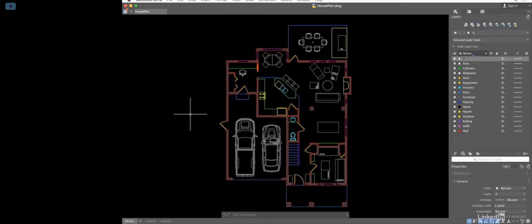that your CAD program can export to a format that SketchUp Pro can import. And I'll be using AutoCAD's native DWG format for this purpose. Most CAD programs will either support DWG or DXF, which are industry standard formats, and these can be brought into SketchUp. However, SketchUp can't import the current version of AutoCAD's format. Instead, you have to save it down a version first, and that's easily done.